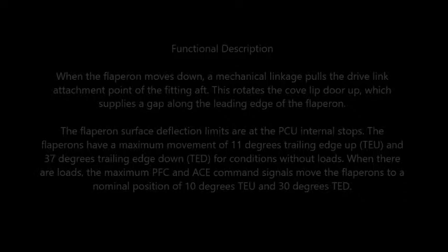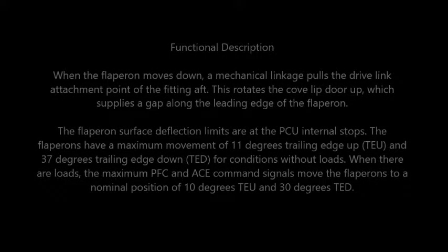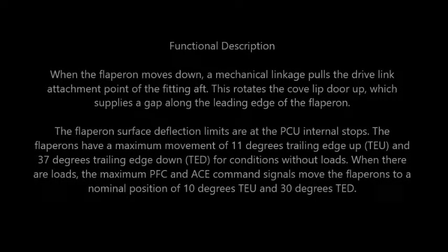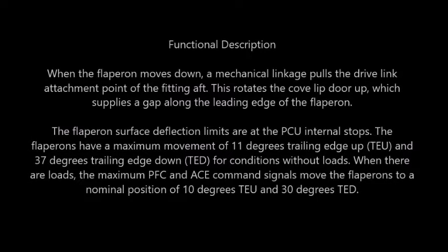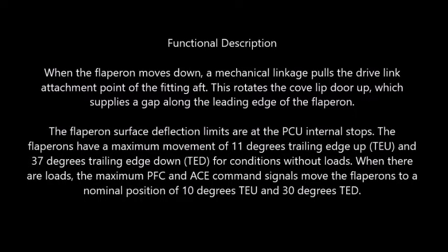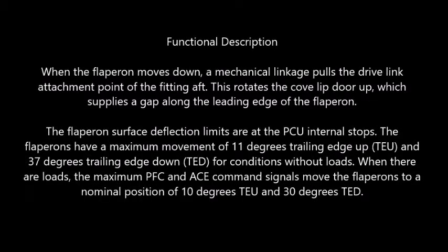Functional description of flaperons. When the flaperon moves down, a mechanical linkage pulls the drive link attachment point of the fitting up. This rotates the cuff lip door up, which supplies a gap along the leading edge of the flaperon. The flaperon surface deflection limits are at the PCU internal stops.